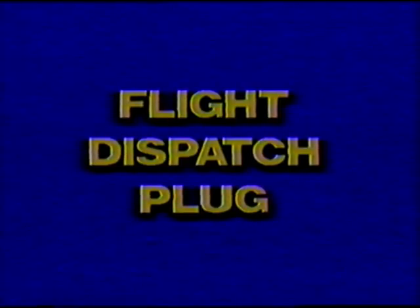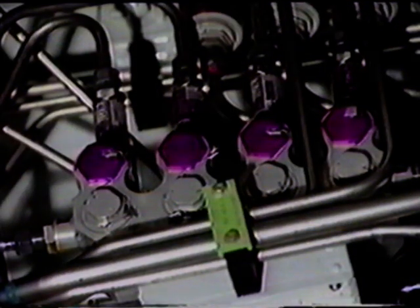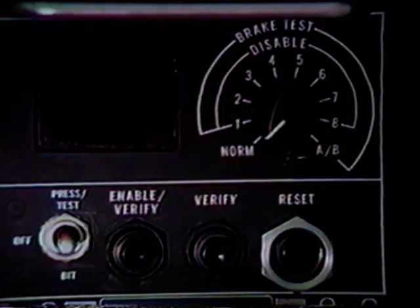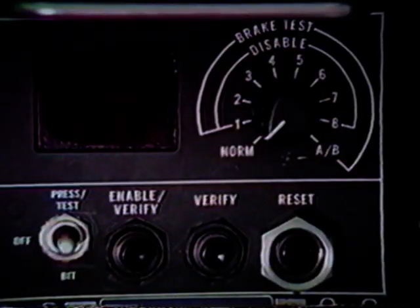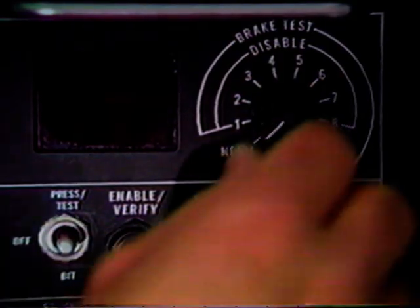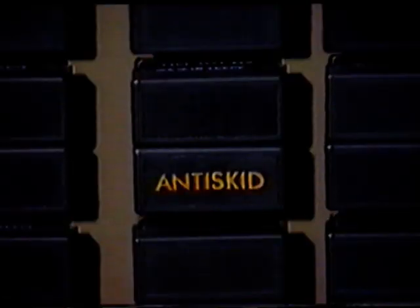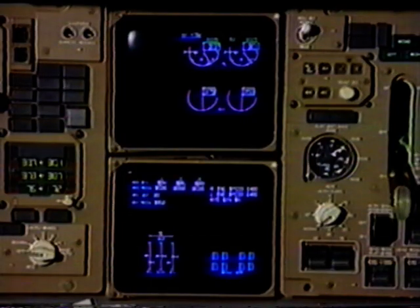A flight dispatch plug is inserted in the shuttle valve module to block the faulted valve output and hydraulically disable the brake. The fault indication may be deactivated for one wheel by placing the switch in a disabled position. This removes the selected wheel from the fault annunciation circuitry to the amber anti-skid light and the ICAS display.